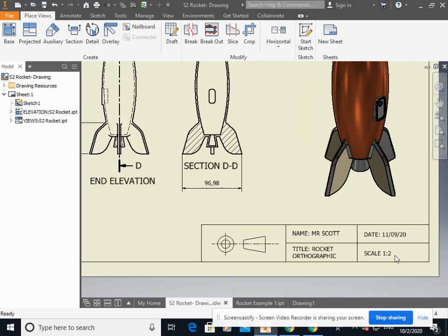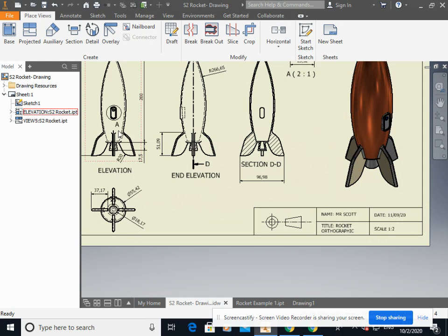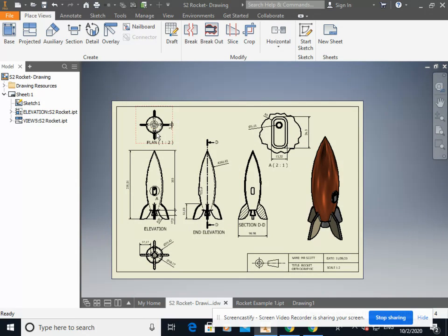scale, and the title. The bit I wanted to quickly show you is this third angle projection symbol. And this is an important feature of orthographic drawings that tells us which way around the views relate to each other. So that tells us that when we look at this view, the plan will be above the elevation, showing a view as though we were looking down, and the end elevation will be shown on the side that we would be standing when we would see it looking like that. So basically this is how the object would look from the right hand side where it's been situated.